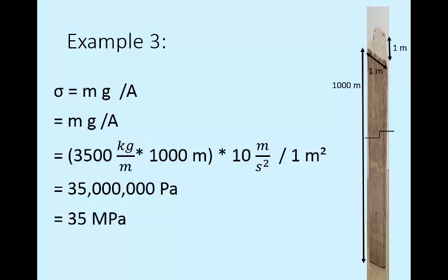This calculation shows that at depths in mines or drill holes, expect stresses to be in the order of the MPa magnitude range. The actual value is going to depend on the density of the rock and the influences of geology. For instance, there are tectonic plates pushing against each other, faults, folding, and so on. All of those types of geological factors are going to influence the magnitude and direction of the forces in a rock at any given location, but stress will still always be in the order of magnitude of MPa.